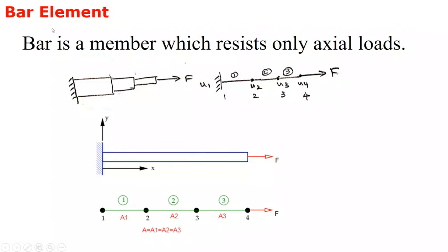Based on that, here they have three stepped bars with three different areas, so at minimum we want to create three elements in a straight line. The second one is the same object, same size, and that can be considered as different elements. It depends upon our convenience. We can convert it into a single element or multiple elements.